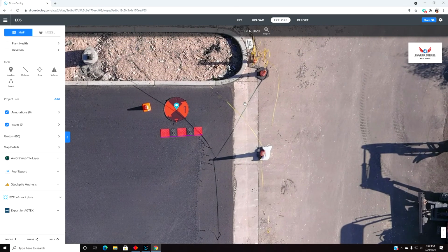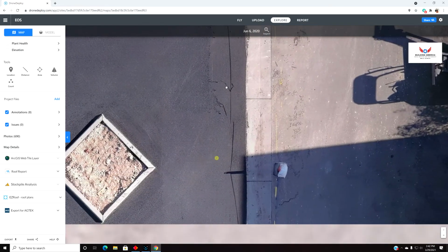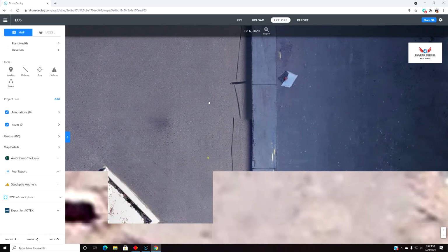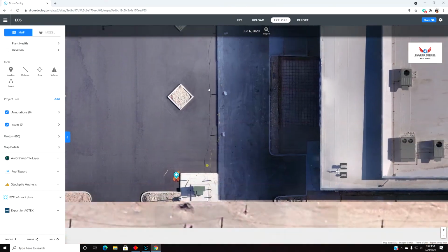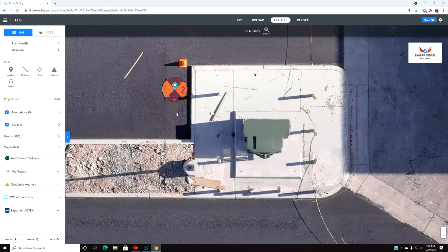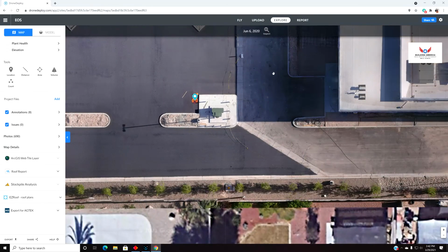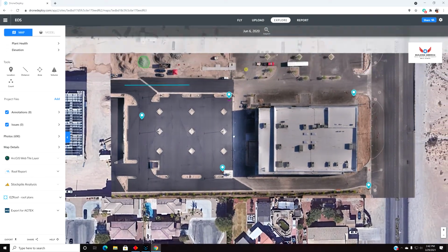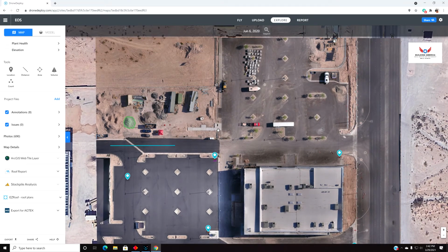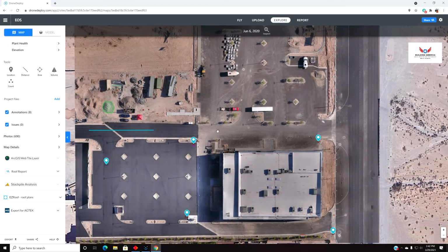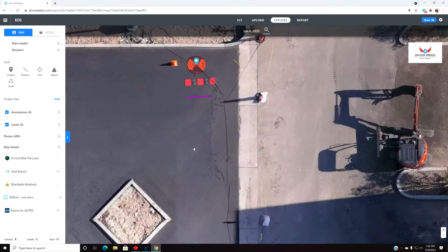and this is with any software, is the ground control points that I lay out in the field and record with a GNSS receiver, a high-end, survey-grade receiver, the same tools the surveyors use on the construction site. I believe this map has 4 ground control points. It's not a huge map, but typically on a map this size you use between 4 and 5 ground control points.